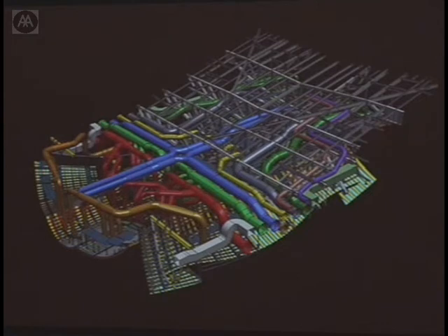In this case, in the roof of the hall, we have these acoustic panels that are basically covering the concert hall below it, and above that we are feeding air from two lateral service towers into the hall from above, and the air gets sucked away from below the seats. Because it's a very precise concert hall, this has to be very quiet. So to maintain airflow, the duct sizes are really, really big. They're over 1 meter wide, so that the air can move very slowly and be quiet.